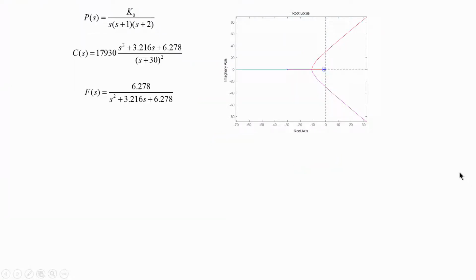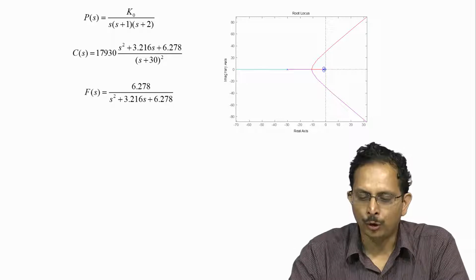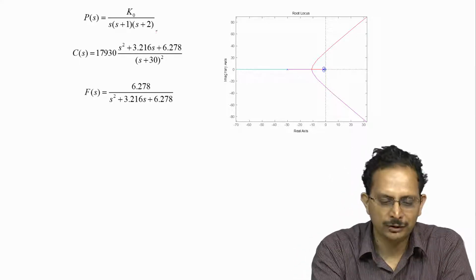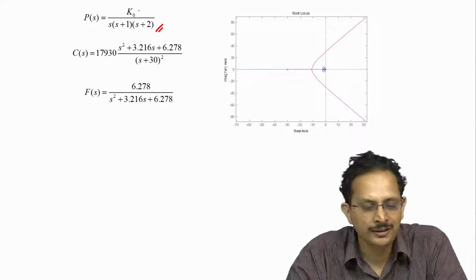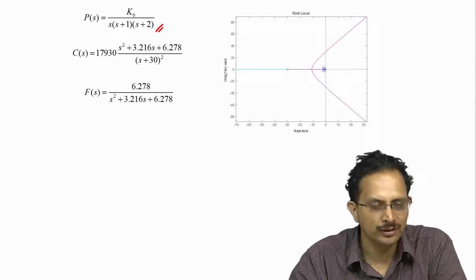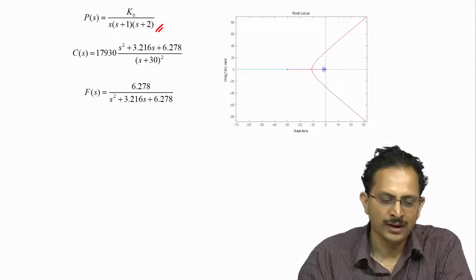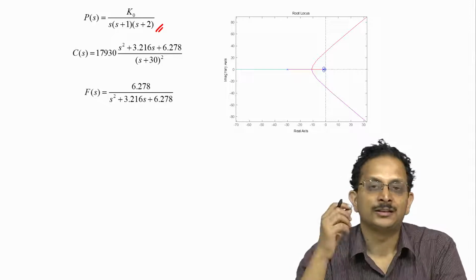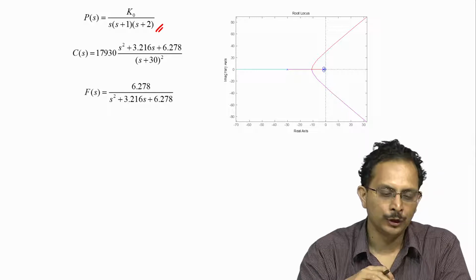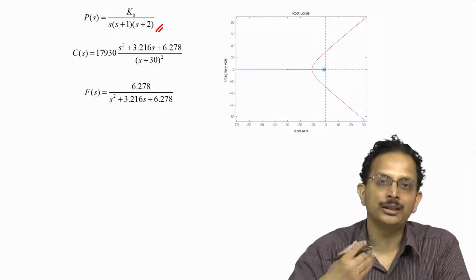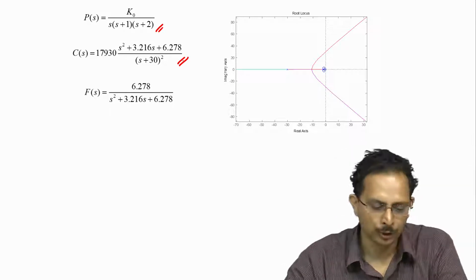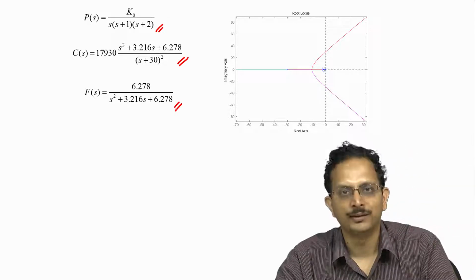I have shown in this graph the overall root locus of the system. So we have this plant whose gain K0 is uncertain. It can vary by a factor of 10, nominally it is equal to 1, but it can reduce to 0.3 and increase to 3. And in order to make sure that the variation in the dominant closed loop pole, due to the variation in the plant's gain, is within 0.4 units, we need to have this as our feedback controller and that as our pre-filter.